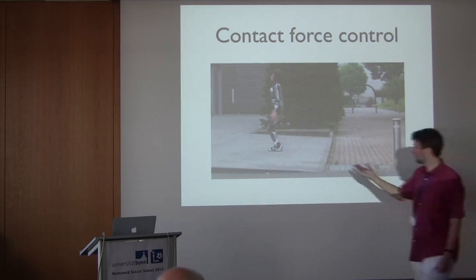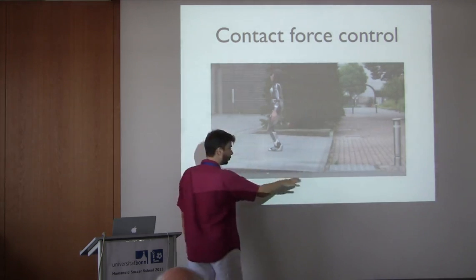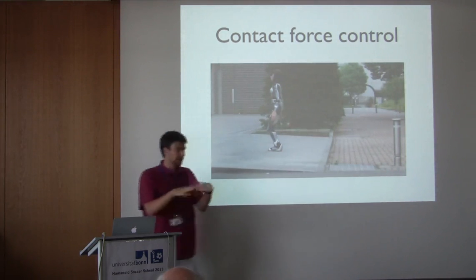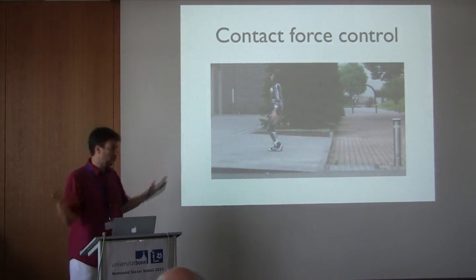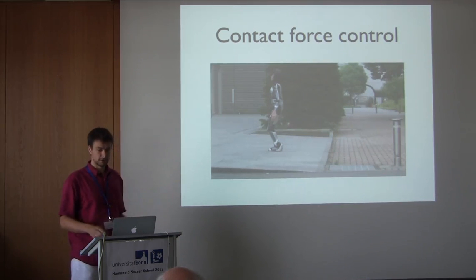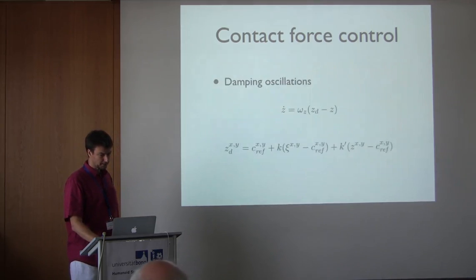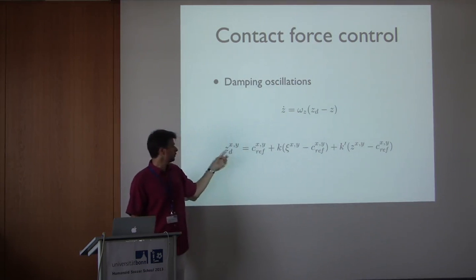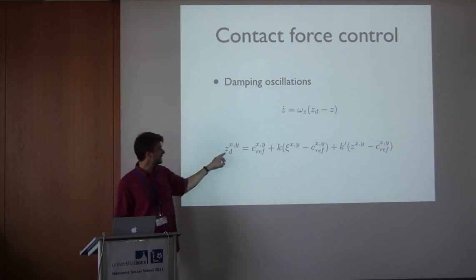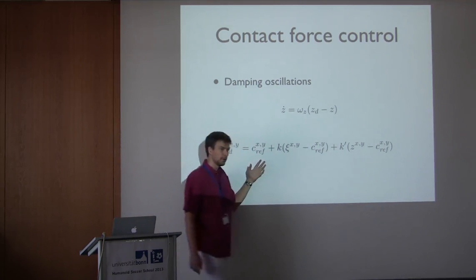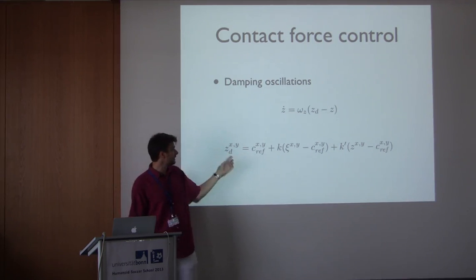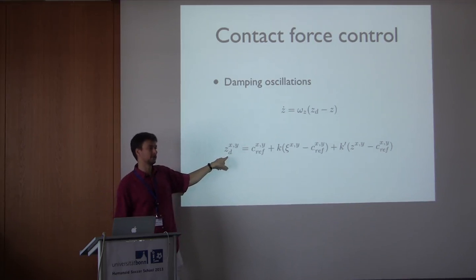So that's the kind of things that you have. So here the slope was not low. The noise here and the dirt here, which have different damping effects, are not modeled, and it's the robustness of the stabilizer. Of course, here you have some controller that gives you where you want to put your center of pressure. What happens if, when you have strong perturbation, you want to put your center of pressure outside of your support plane? Okay, with this equation, it gives you Z should be here, it's outside your support plane.